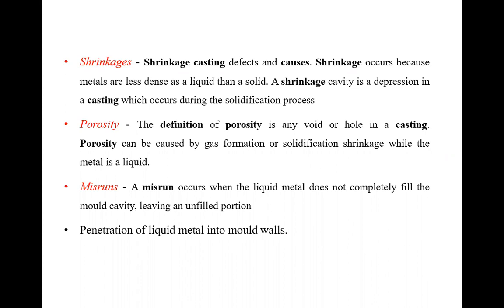So we had already arranged a runner, and from the runner we can see the excess metal. Clear? The metal has to flow continuously into the gates so that there are no defects, so that whatever molten metal is required during solidification is taken in.